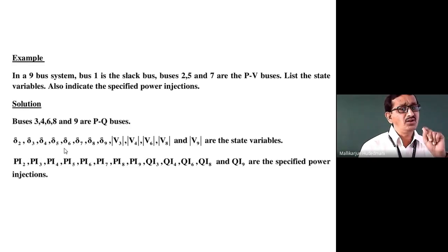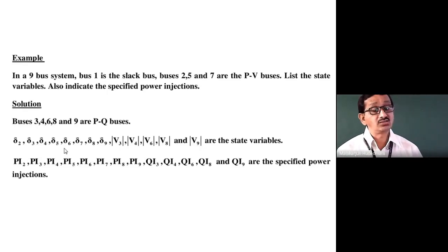Having understood this simple dimensioning, you will come to know the massive work involved in a power flow solution. Imagine a 1000 bus system, a Y bus of 1000 cross 1000 dimension, and all these connected things in a computer. Just imagine the vast connectivity and dimension of the problem. It cannot be done by a human.